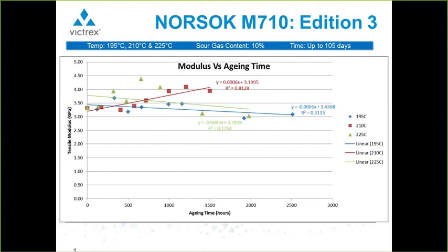Once again, and coming back to my old friend modulus, modulus is doing all sorts of strange things even at these different temperatures and different times. Once again, kind of supporting the notion that it's a confusing picture to use modulus for thermoplastics, and it becomes very difficult to estimate the half-life of the material, the lifetime of the material, based on modulus alone.